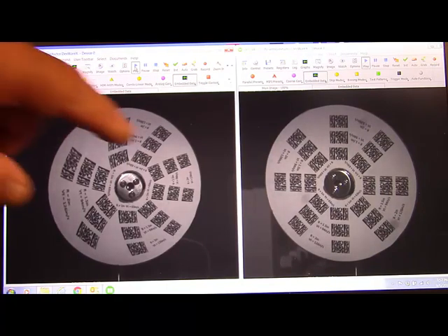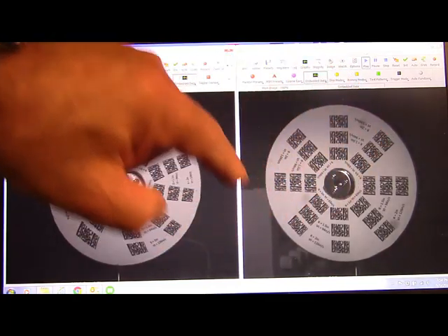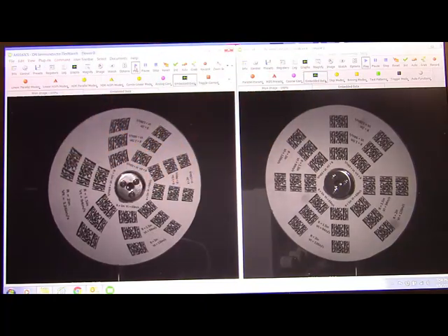One problem area for global shutter devices is that these storage nodes can be susceptible to light leakage, which can cause blur and banding in the image. The AR0144 has been developed with significant shielding, which delivers a global shutter efficiency of over 4,300 to 1, which is more than double that of similar products in the market. This means that the AR0144 can deliver a clear image for the user. This leading global shutter technology efficiency is combined with a design that is focused on high SNR or signal-to-noise ratio and a low overall noise, which delivers a leading performance in its class.